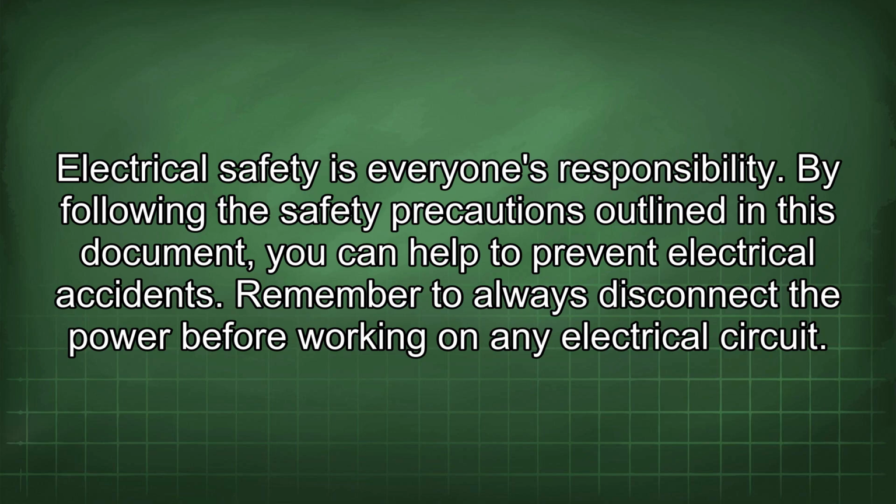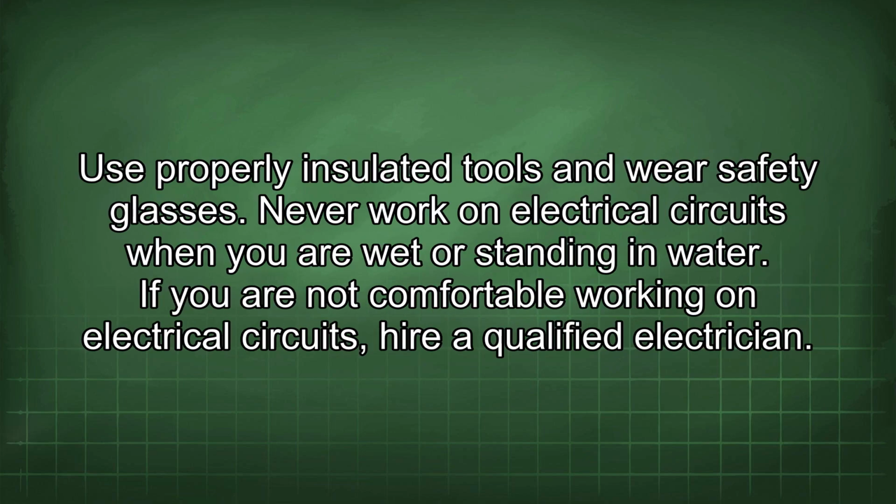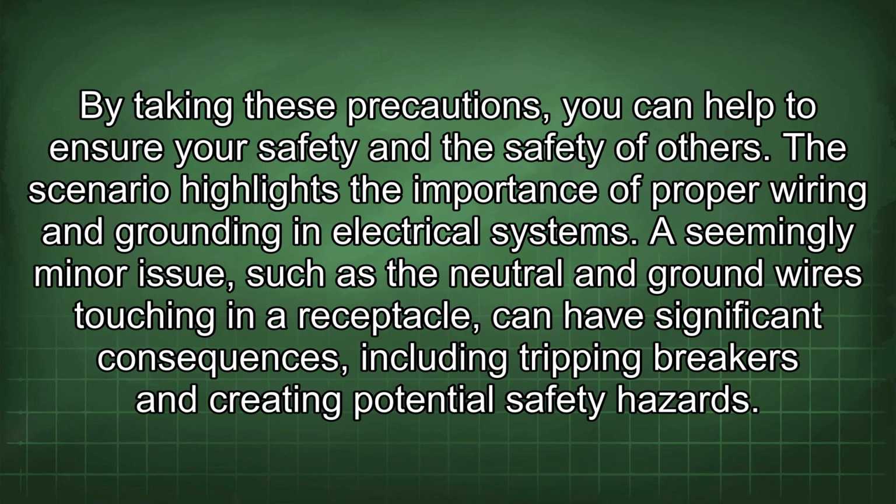By following the safety precautions outlined in this document, you can help to prevent electrical accidents. Remember to always disconnect the power before working on any electrical circuit. Use properly insulated tools and wear safety glasses. Never work on electrical circuits when you are wet or standing in water. If you are not comfortable working on electrical circuits, hire a qualified electrician. By taking these precautions, you can help to ensure your safety and the safety of others.